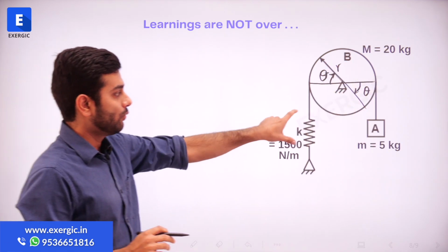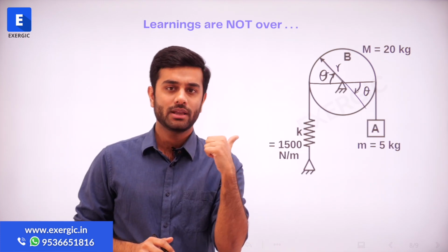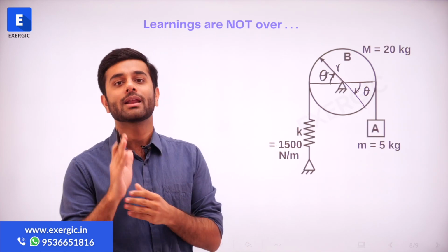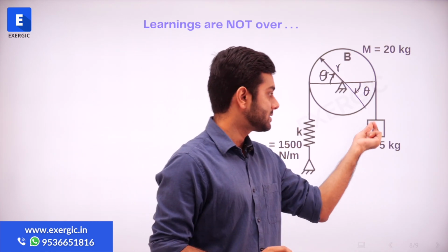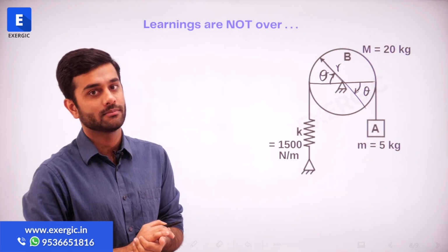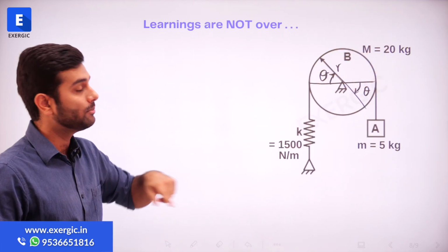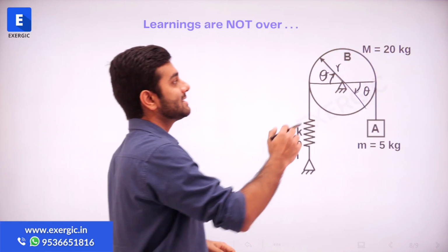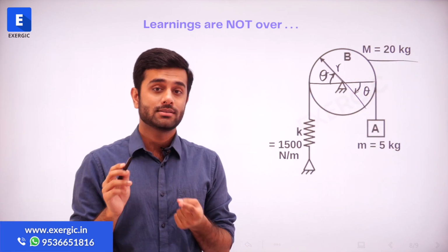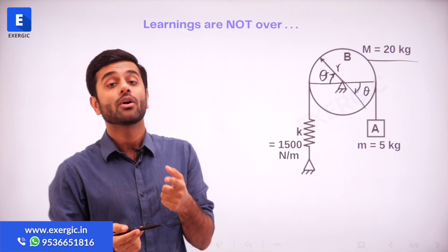Now, this force, spring force, is a linear force. It is not a torsional spring, right? We have torsional spring in the question also. It's a linear spring. So it will apply a linear force. Similarly, this mass here also accelerating will have a linear inertia, right? Not the rotational inertia. But this pulley, its mass is also given. Again, this is another important point to note here. Since mass of the pulley is given, its inertia is also going to get counted. This is another thing where question can trick you. In some cases, it may give you the mass or it may not give you the mass.